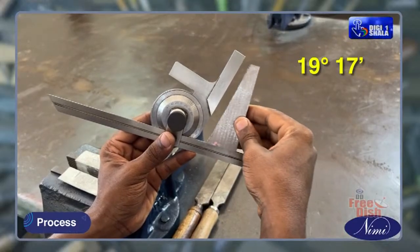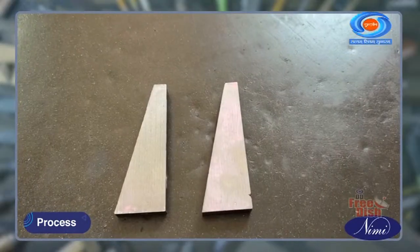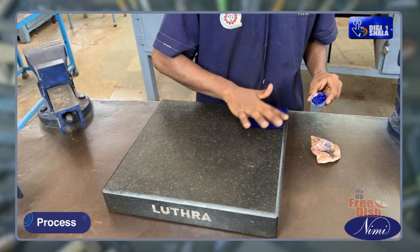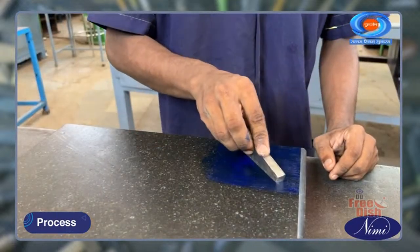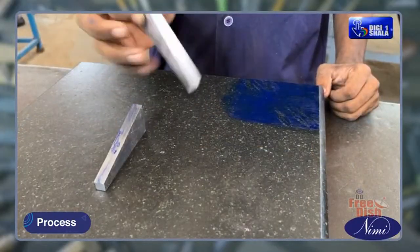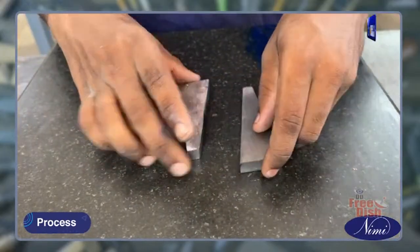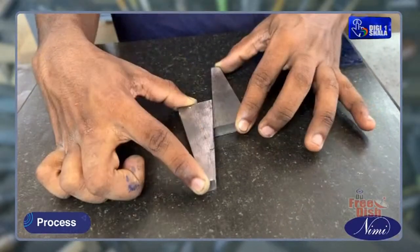Similarly, file part 2 to size and shape and also to angle 19 degrees 17 minutes. Apply Prussian blue evenly on the surface plate to check high spots on angular surfaces. Place part 1 and part 2 angular surfaces on the surface plate and move gently. Take the job from the surface plate and notice the high spots, the Prussian blue spotted marks, on angular surfaces.